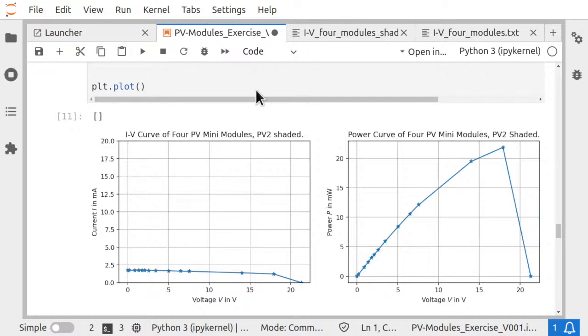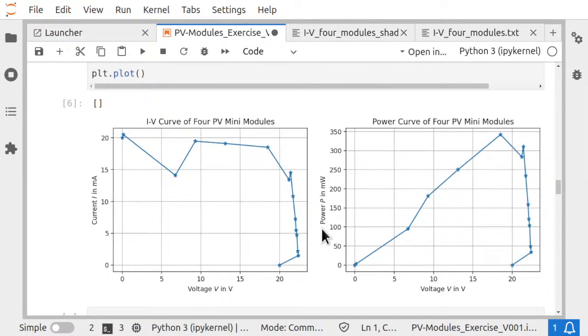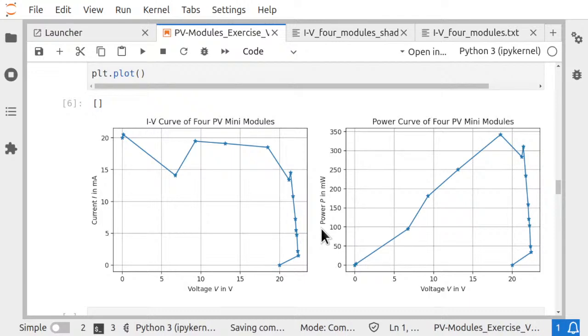Do you remember what is the maximum power point in this diagram? So we have these points, and each of these points has a voltage and it has a current. And the product of it is the power for this point, for that point, for that point. And at one of the points of your measurements, it's max. Here. It's this point. So this is the maximum power point.